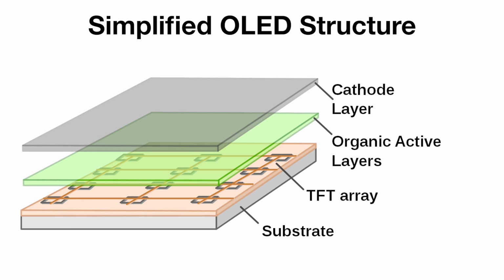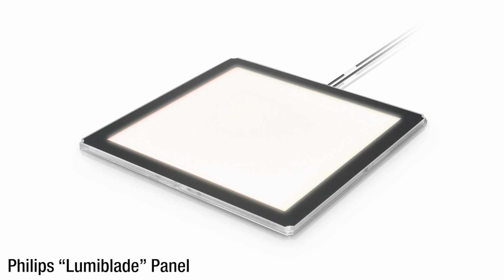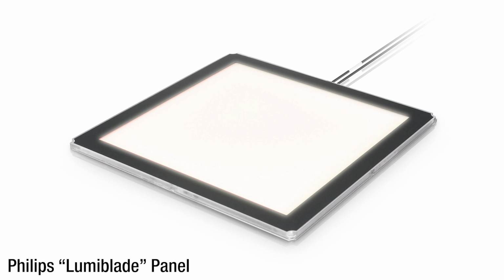Then what you can do is energize those 2 sheets, and depending on how big they are, they could even be the size of a single pixel, and it just energizes all the molecules between them at once so it all lights up. In other words, OLED can be deposited as a film between 2 layers which act as anode and cathode, and whatever parts of that film get power will light up. This means you can have squares of OLEDs, for example, that are not really an individual point of light, but rather an entire square that can light up uniformly.